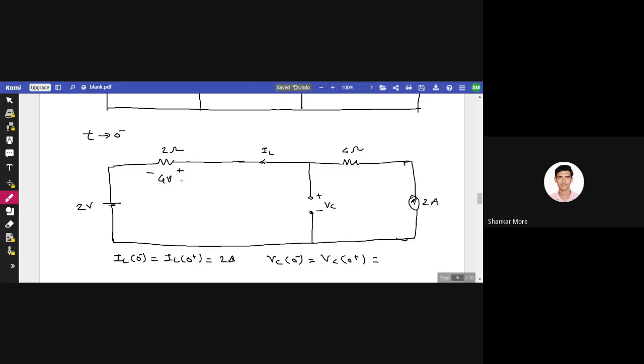Now this is positive negative, that means they are in series and they are going to add. So voltage across these terminals will be what? See, if there is some voltage here, it should be 6 volt. Okay, it is 6 volt. Do you agree with me? 6 volt. Does anyone have any doubt, if something else could be possible here?